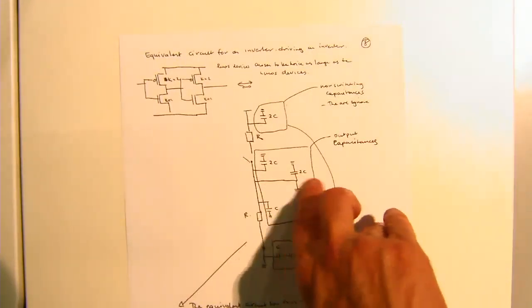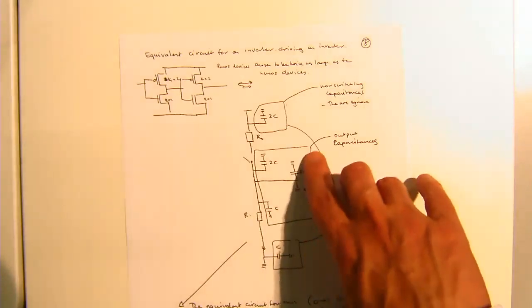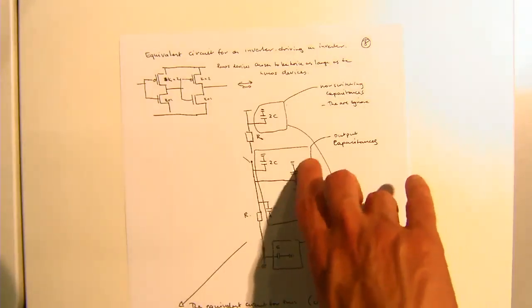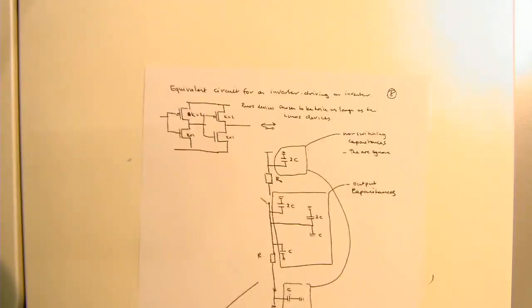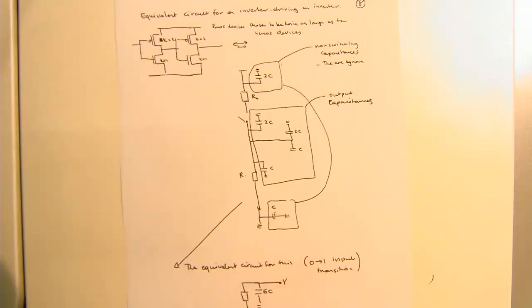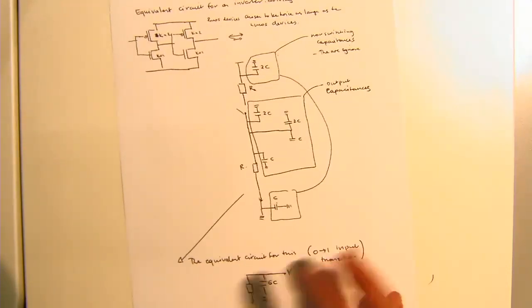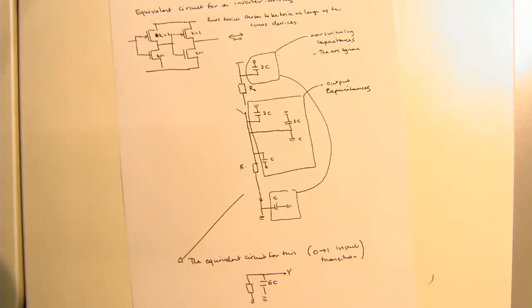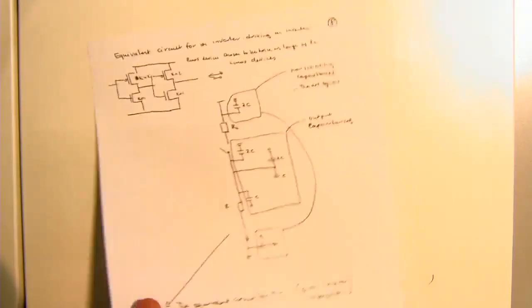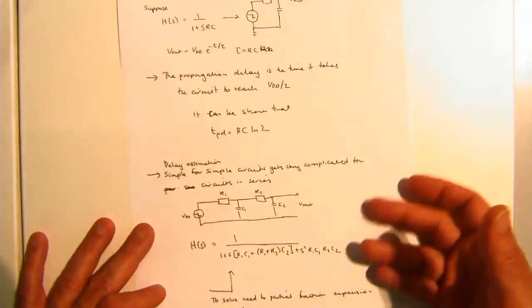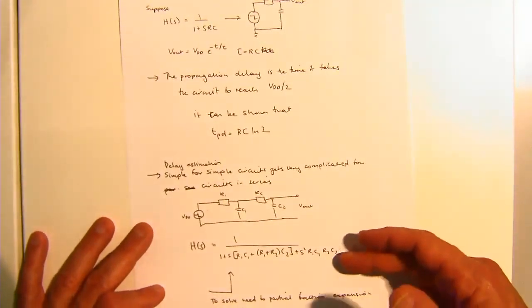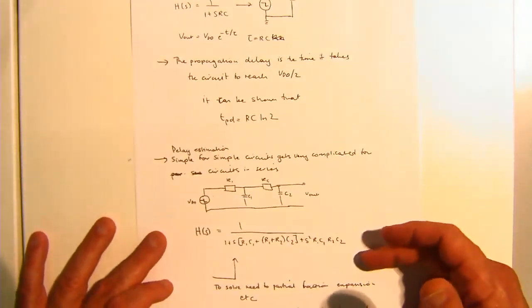And here we're also driving the capacitance of the next gate. So essentially there, what we did was work out an equivalent circuit for this. So therefore, we can say, well, if we've got this RC circuit, how quickly can we get it to decay or go from a 0 to 1 transition? And the last thing that we did was we talked about transient responses and showed how it gets really complex very quickly when you're trying to do your standard Laplace type transfer function approaches.